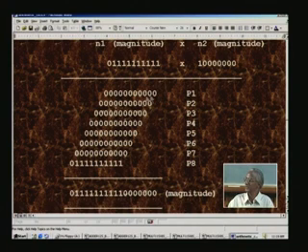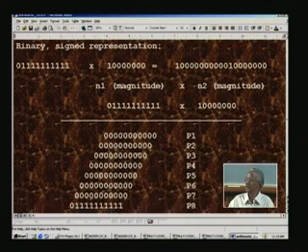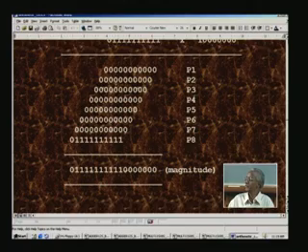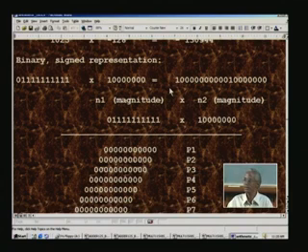Let us give a nomenclature to each of these partial products, which is the multiplication of n1 with a single bit of n2. The LSB will be the first here, and all other bits will be in this fashion, and out comes this result, and this is in magnitude form, whereas what we have put here is in 2's complement, which signifies a negative number. This and the last number are equivalent actually, so we can find it out from this. If you take 2's complement, as I mentioned, you will get the magnitude straight away. So we are not bothered about the negative number, because what we are interested in is only evaluating the magnitude.